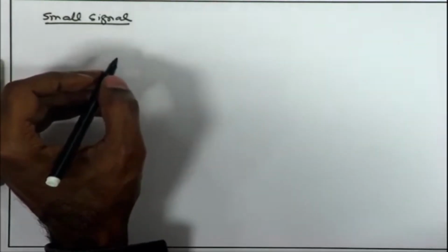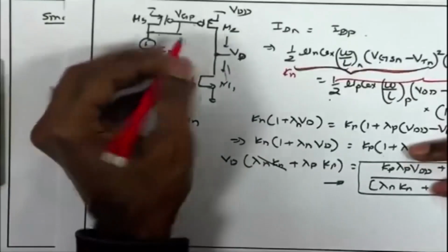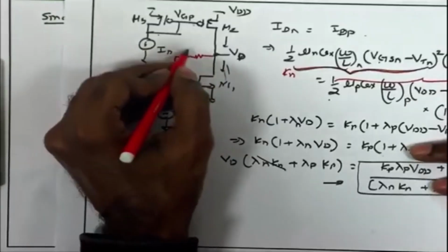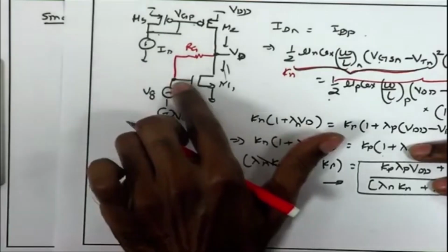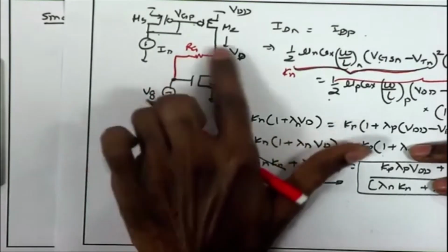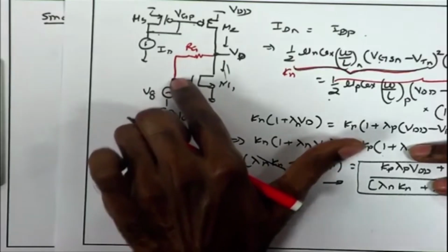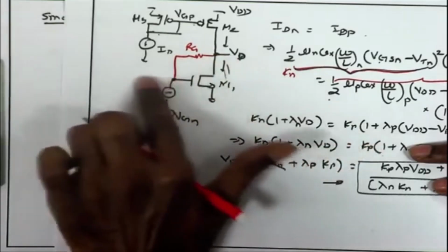So, here also there are certain mechanisms through which Vd can be fixed. One example is, you can just use a very large resistor over here, Rg. This can help us in establishing an appropriate DC bias for Vg. You can think of why, because in this case the DC voltage at the gate is going to be the same as the DC voltage at the drain, provided you have AC coupling over here.